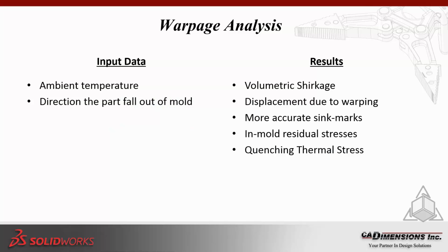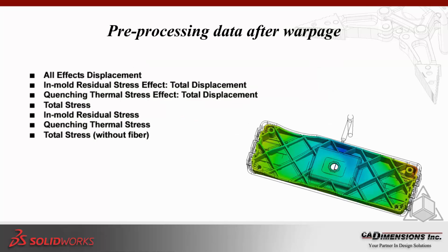Before the last thing I wanted to show you, I wanted to again just go over some of the results we get from warpage. Of course, all effects of displacement, so X, Y, and Z, the total stress, the in-mold residual stresses, so you can identify high stress areas, and again, a lot of these results will also affect your flow and pack analysis.